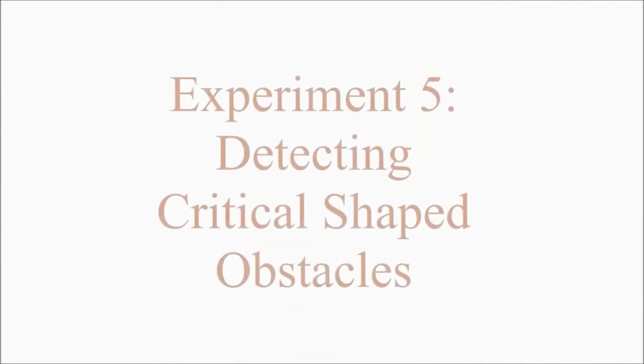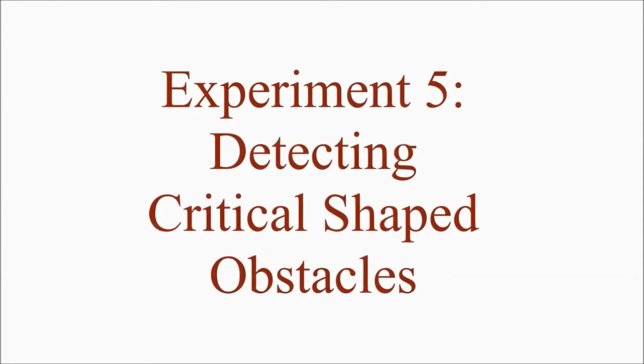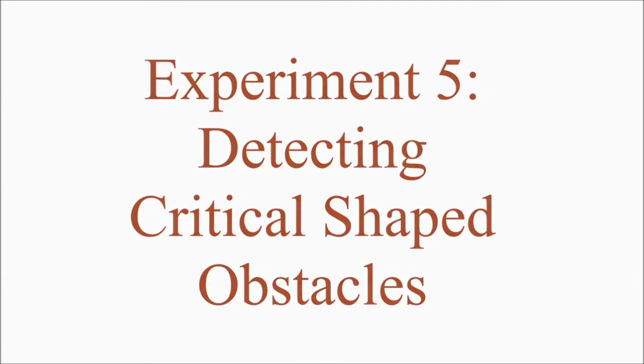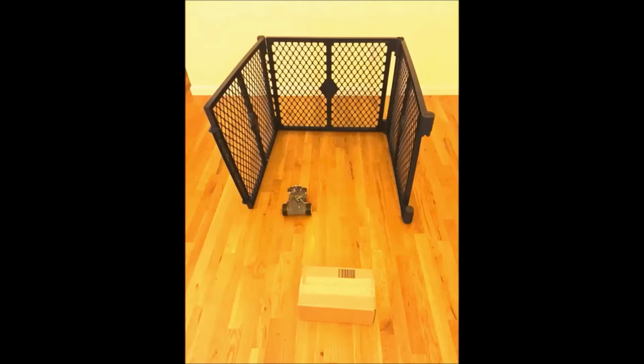The proposed model is unlike two other reported algorithms. It guarantees a collision-free path from simple to critical environments including U and H-shaped obstacles. In the case of a U-shaped obstacle, the robot senses the side walls, calculates the distance to the front wall and steers inside. As the front wall is detected, the robot turns about 90 degrees to avoid it, and then it turns about 90 degrees again when the side wall is detected. After avoiding a U-shaped obstacle, the robot continues its motion in that direction.